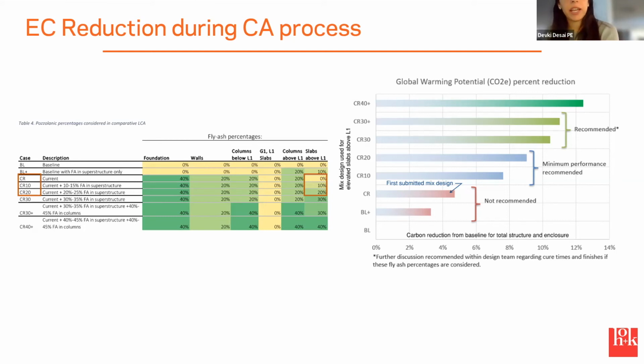And I know I might be kind of waxing poetic about concrete right now, but that's because it is incredibly crucial to the sustainability of your project. It really comes down to the mix design. And given what we saw with the net zero lab results, how large a piece of the total carbon puzzle foundation is, it can be a little bit out of sight, out of mind, but a lot of your carbon emissions are in that concrete foundation that's underground. So if we go to the next slide.